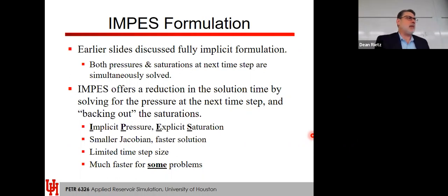But I'll show you some examples where we run models with some pretty non-orthogonal grid blocks, and we've lived with it and accepted it, and we've tested it. All this is really just to illustrate some of the impacts of things you might do to your model. Like if you impose some highly non-orthogonal grid blocks, you might have to run it in 11-point formulation, and that might make it twice as fast to run. I don't know. It might take a lot more time to run. So it might be better for you to go back and regrid it without that if you find that to be an issue.